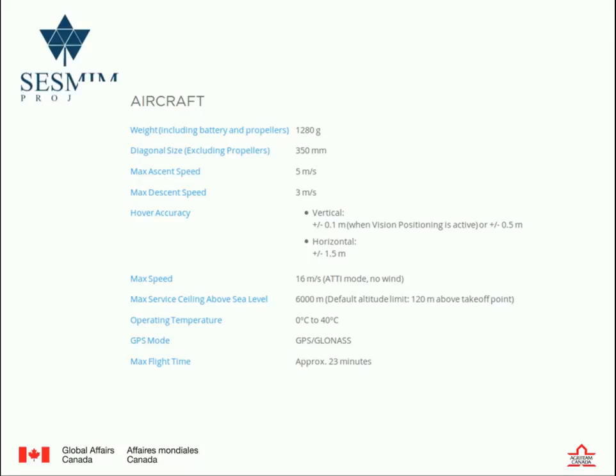the problem is if you have the drone coming back and you say, well, it says 23 minutes, you plan for 23 minutes. Well, if you're 3 minutes out and it goes to 0, it is a flying brick straight down. I would err on the safe side, make sure you have maybe a smaller flight area, but to make it come home in time before the batteries die.